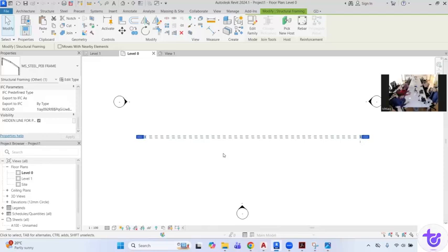But if there is a requirement that you cannot change the detail level of a view, and it is recommended to use the fine detail level in every view, then there are constraints with the visual style. That is not good. The subcategory is better, a good solution for this kind of thing. This is applicable to all families, wherever you want, you can create a subcategory.